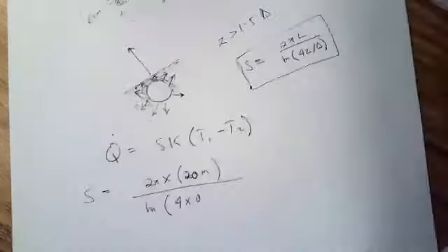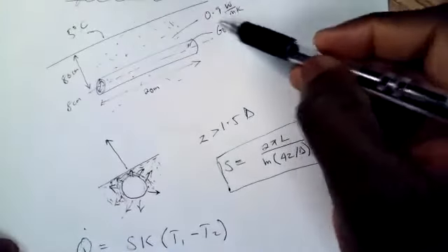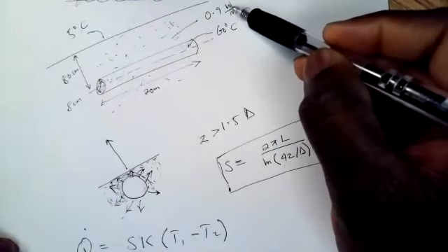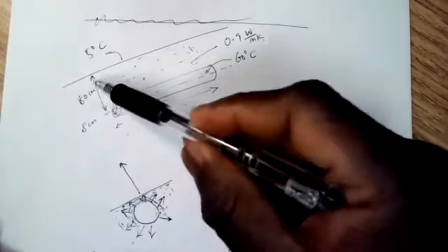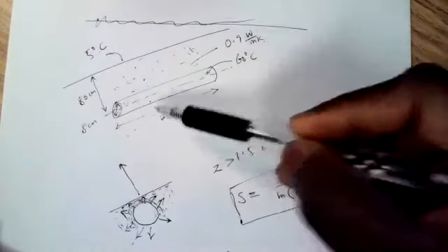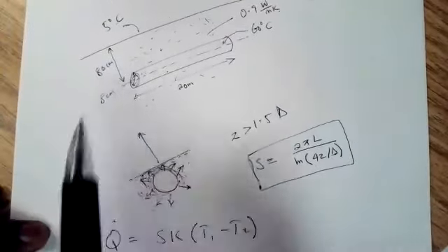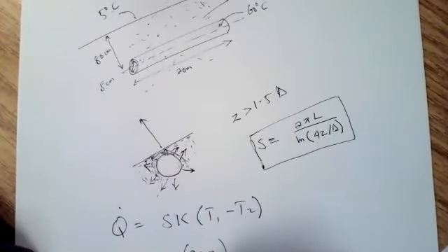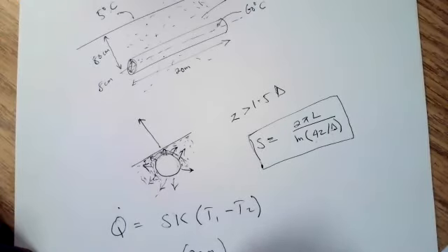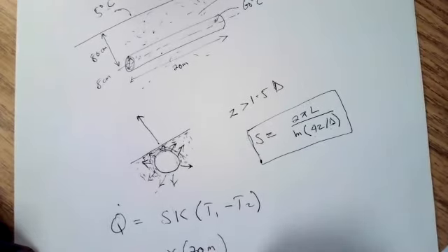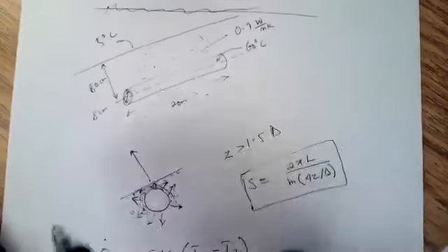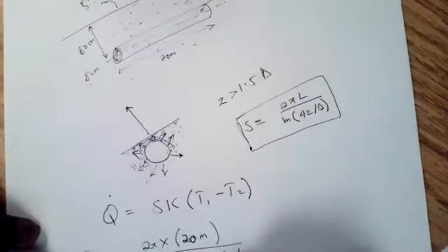Yeah, so as I was saying, don't mix up your units. You've been given watts per meter Kelvin. It is easier to change these to the standard units than to change this to match this. So 80 cm, divided by 100, we get 0.8 meters, and then this is divided by the diameter, which we had as 8 cm. If you divide it by 100, you get 0.08 meters.